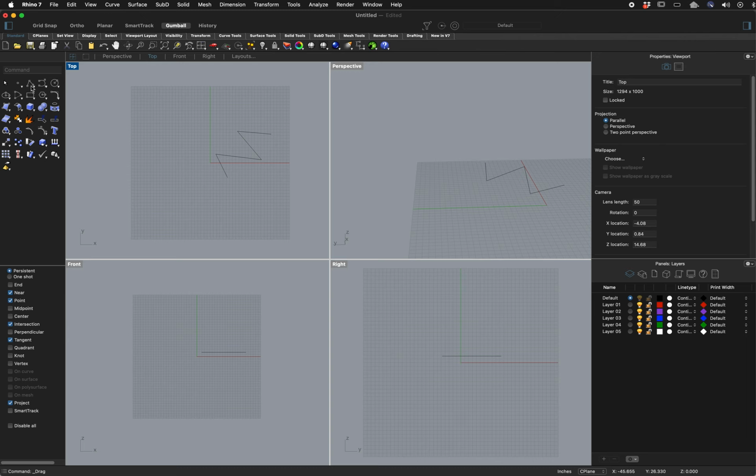Additionally, this is called polyline. You can also call a command up simply by typing it in the command menu, and that calls the tool up again. And also, if you want, you can type in locations. So here I'm putting the first point at 0, 0, 0. That means it will be located right at this point right here. So if I hit return, you can see the first point has been located at 0, 0, 0.